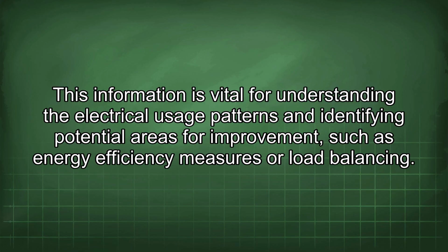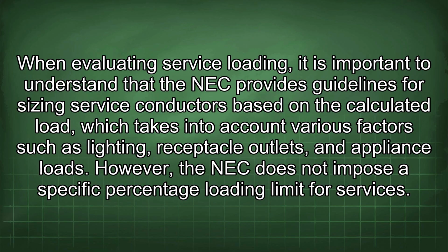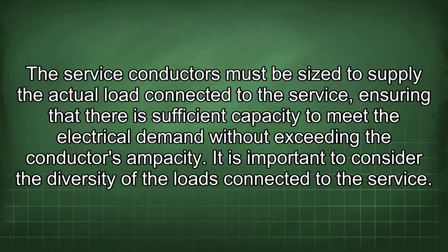When evaluating service loading, it is important to understand that the NEC provides guidelines for sizing service conductors based on the calculated load, which takes into account various factors such as lighting, receptacle outlets, and appliance loads. However, the NEC does not impose a specific percentage loading limit for services. The service conductors must be sized to supply the actual load connected to the service, ensuring that there is sufficient capacity to meet the electrical demand without exceeding the conductor's ampacity.